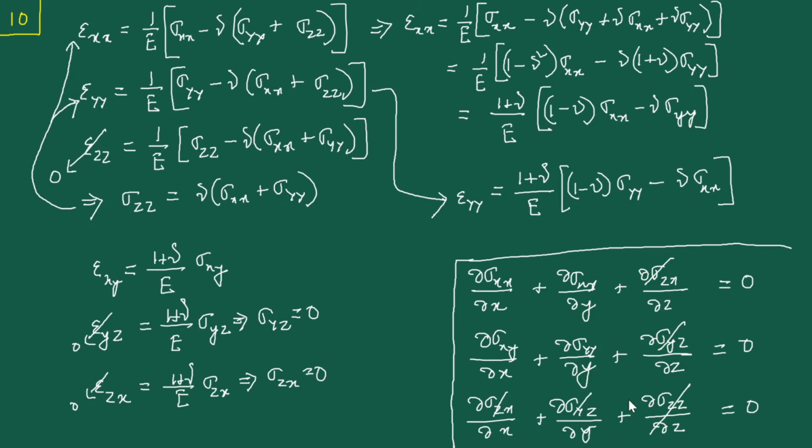So overall you see that we have ended up with only these two equations involving the sigma xx, the sigma xy and the sigma yy, just like we had done in the plane stress case. This is very interesting, and it gives us hope that whatever we were able to do with the Airy stress function approach in the plane stress case, we should be able to do in the plane strain case also. Of course, there are going to be some differences, as we'll see.